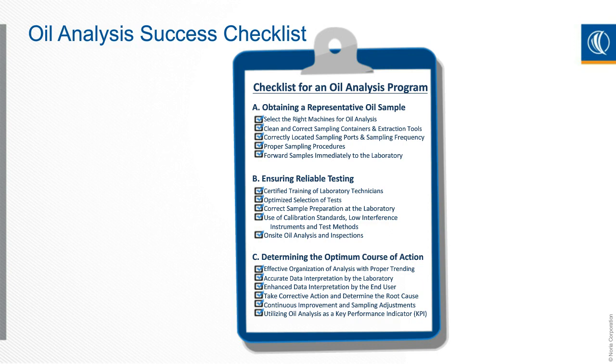Using clean and correct sampling containers and extraction tools. Correct sample location ports and sample frequency, both very important. Probably could be separate checklist items here. Proper sampling procedures, making sure it's a consistent and correct procedure. And then forwarding that sample immediately to the laboratory. So you don't want that sample to be sitting on your desk for several weeks when the information in that bottle could indicate a failure, and by the time you get that result, it could be too late.